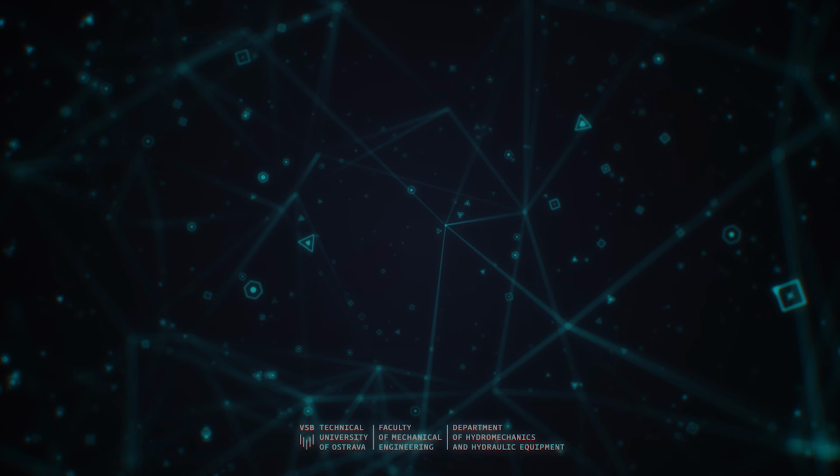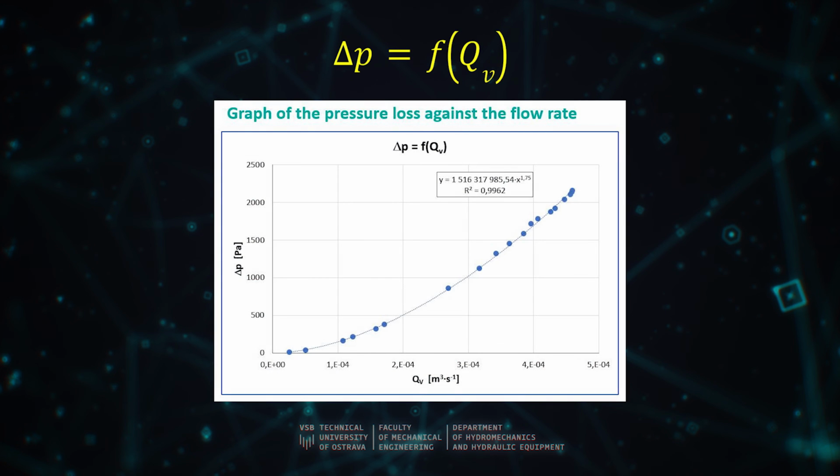We construct the dependence of the pressure loss on the volume flow. Delta P is a function of volume flow. We plot the dependence for pipes with different diameters for comparison. Using regression, we determine the type and coefficient of dependence using Excel, the trend line.